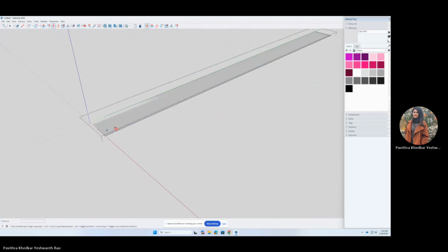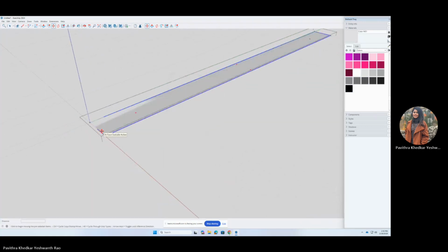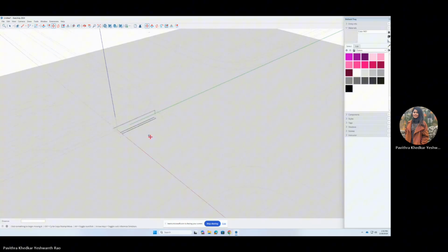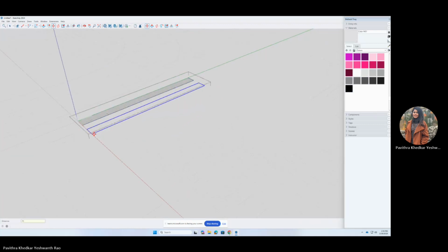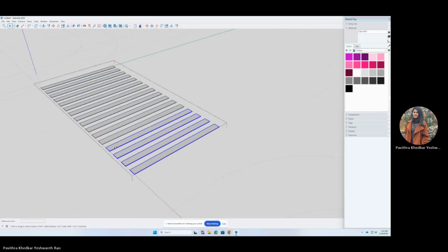Assigning a unique material and color is very important. Apply a distinct color from the material palette to the decals. Make sure that you don't apply this color to anything else in your model. This makes it easier to adjust in the rendering software later.